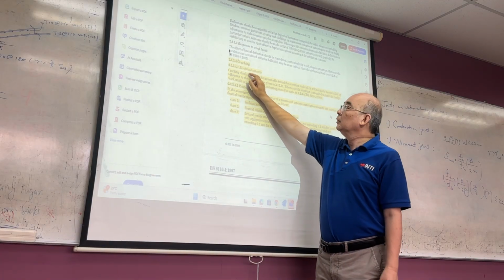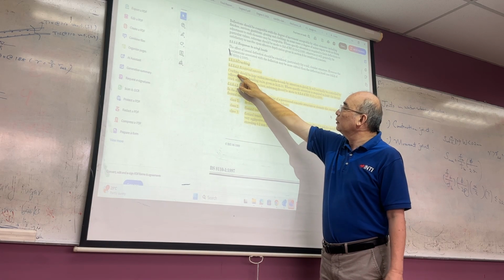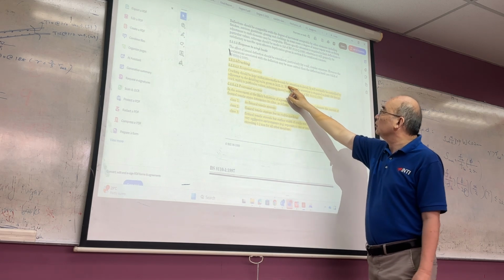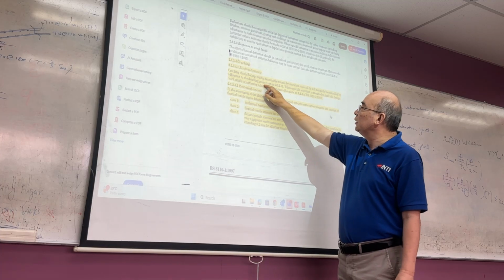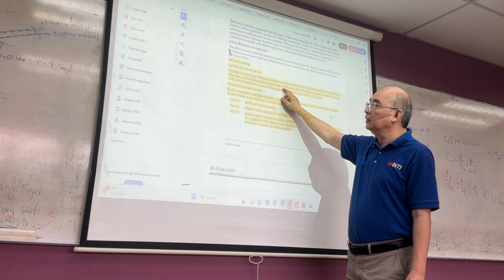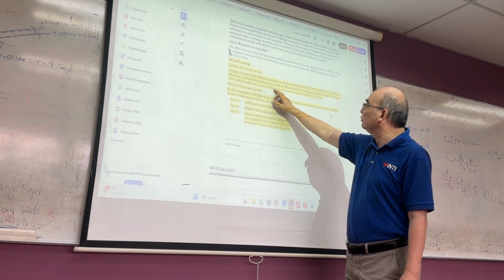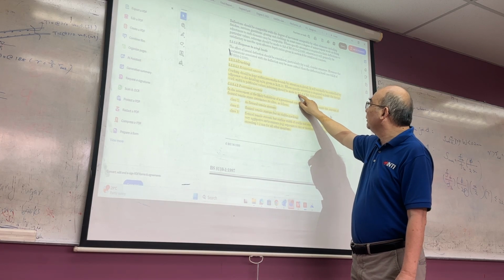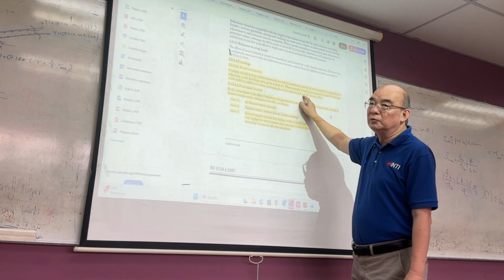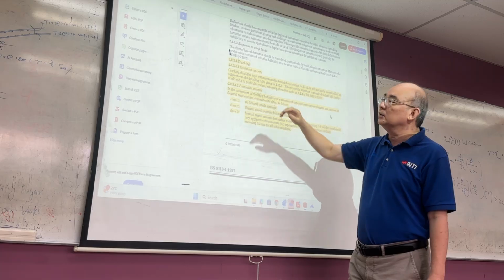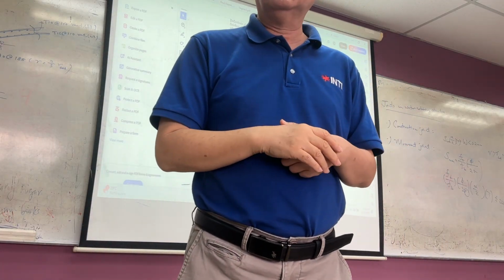Cracking, reinforced concrete. So cracking should be kept within reasonable bounds by attention to detail. It will normally be controlled by adherence to the detailing rules given in 3.12.11. Where further attention is required, for limiting the design crack width to particular values, reference should be made to BS 8110 Part 2, 3.2.4. So what this clause tells you is that reinforced concrete actually has cracks.